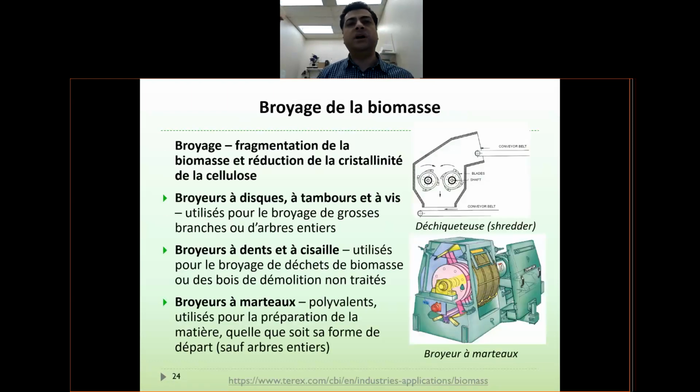Due to the fact that in biomass we always have some volatile composition, under drying those volatiles evaporate, and so they make smells, and sometimes they are toxic. Plus, the biomass itself after drying can be broken into smaller parts, so you have dust production.